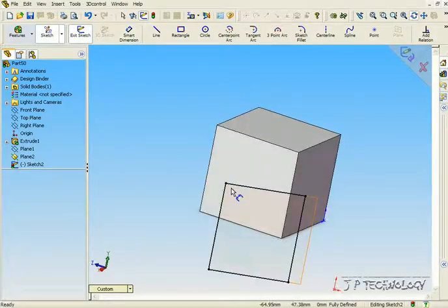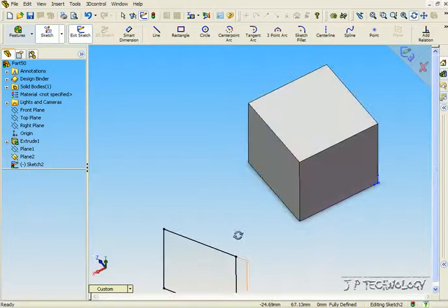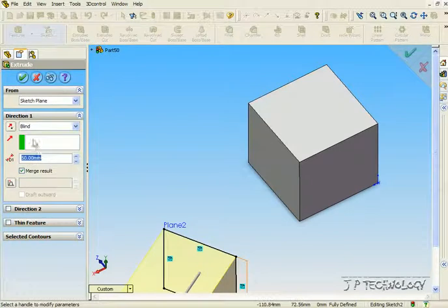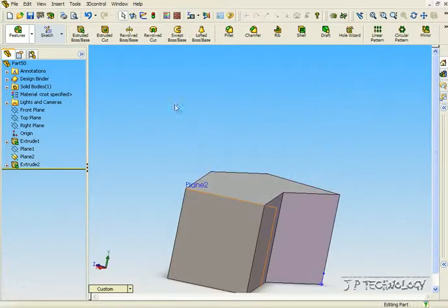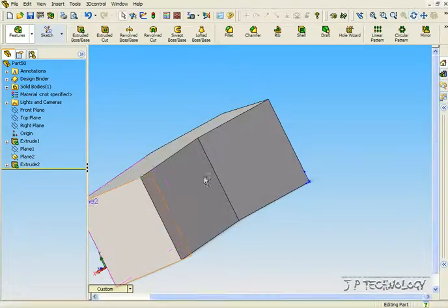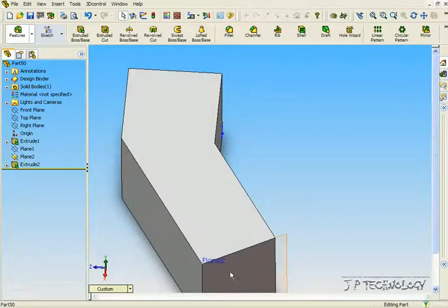And now let's say that we wanted to extrude this. This is going to extrude directly onto those two points, like onto these lines. So when we go to extrude it, it's precisely in the right orientation, the right direction and everything. So it works out very nicely when you convert entities. So let's click Feature, click Extrude, and let's flip it around just so it goes through. Click OK. And you can see that as we extracted those points out of the sketch, it came out perfectly from our extrude. It went perfectly into our original solid that we came out with.